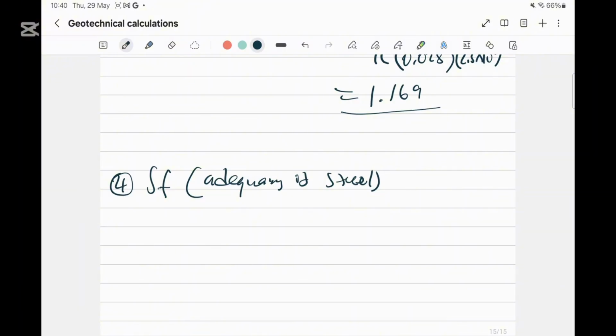For cheap bolts, when you're calculating SF, you might find that it's giving you a smaller number than the SB, meaning that based on the bolt you have in your possession, that bolt won't be able to sustain a spacing of 4 point something, because we got 4.2.